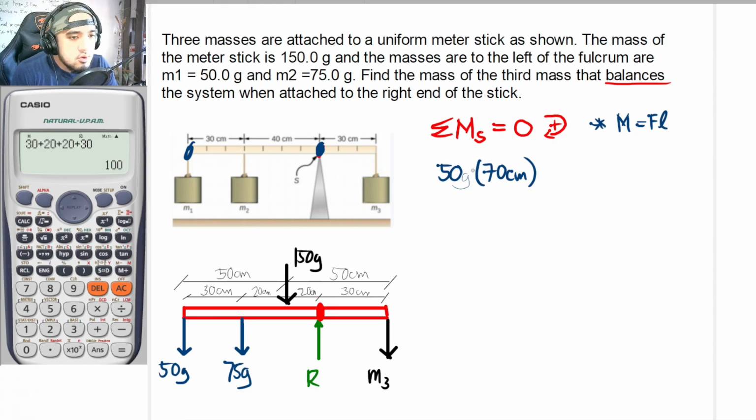However, what is now to be our sign convention here? If this is now to be our point, and this is now to be the force, the tendency of the force is to rotate point S in a counterclockwise direction. Thus, this should be negative because my sign convention is clockwise positive. For example, if you want it to be counterclockwise positive, your sign convention would just be reversed, but your answer should exactly be the same.